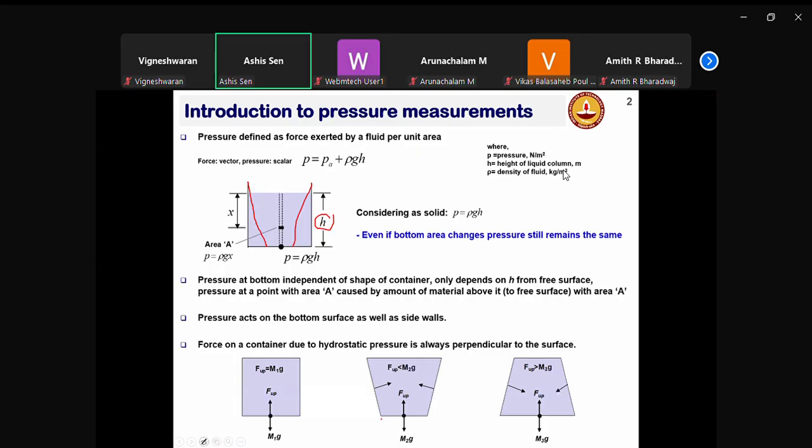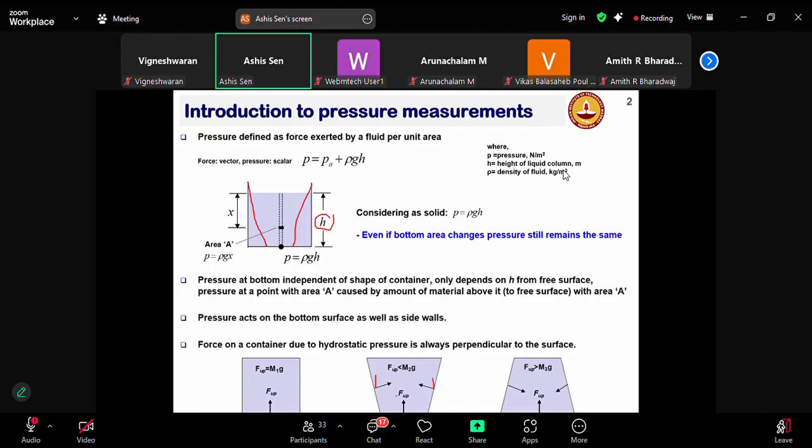But when you make the area smaller with these slanted walls slanting inward, then you would see that this force balance is not satisfied at the bottom surface. If you do a free body diagram of this fluid element, there is some reaction force coming from the wall. And this reaction force has a vertical component, right? So now the vertical component of the reaction force on the side walls plus this upward force would equate mass times gravity. This is how the force balance is ensured here, because mechanics should work.